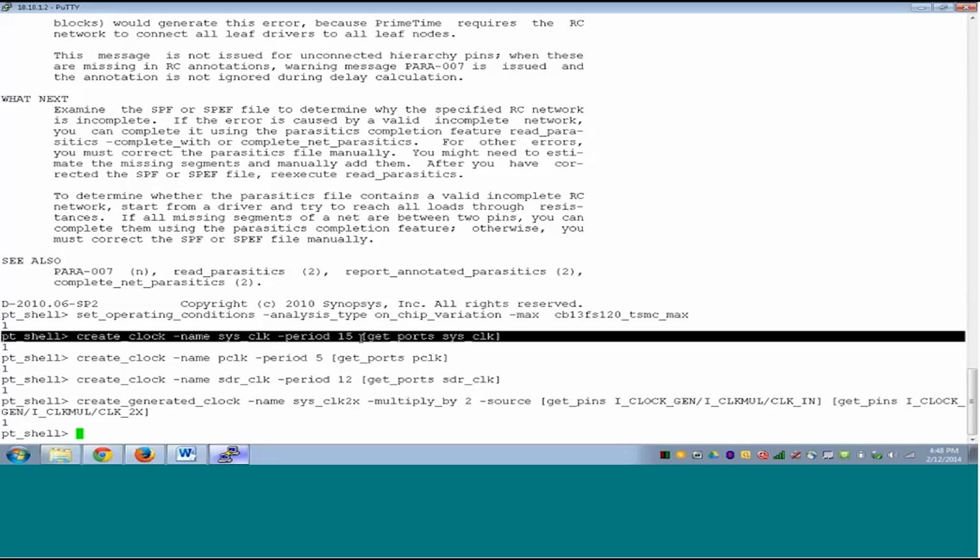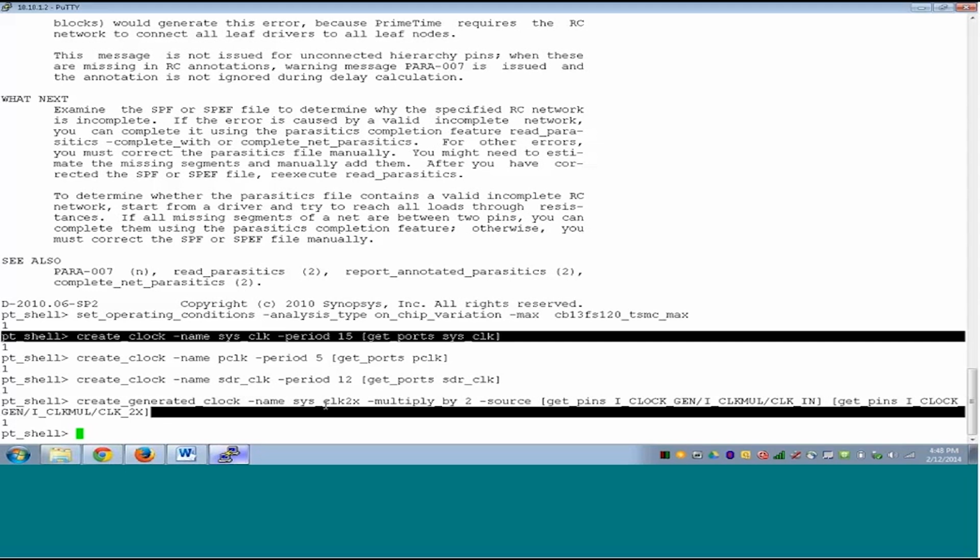In most cases there is no reason to provide two synchronous clocks at the chip level, or even at a layout block level, unless it's an absolute necessity. If the two clocks are coming from two separate PLLs, it does not depend on what period they have, they should be declared as asynchronous. The other case is the generated clock.